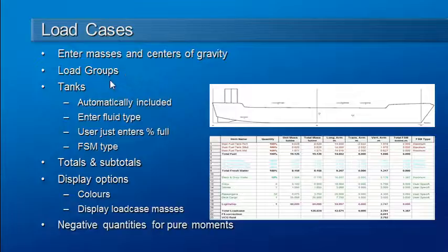the vessel. Tanks which have been defined in Hydromax are automatically included in the load case, and all we have to do is enter the percentage full in order to define what the total mass is, and we'll also demonstrate in a moment how to deal with the free surface effect of any fluids in tanks. The load case can have entries inserted to automatically tabulate totals and subtotals, and I'll also show you some display options for color coding loads and displaying load case masses.